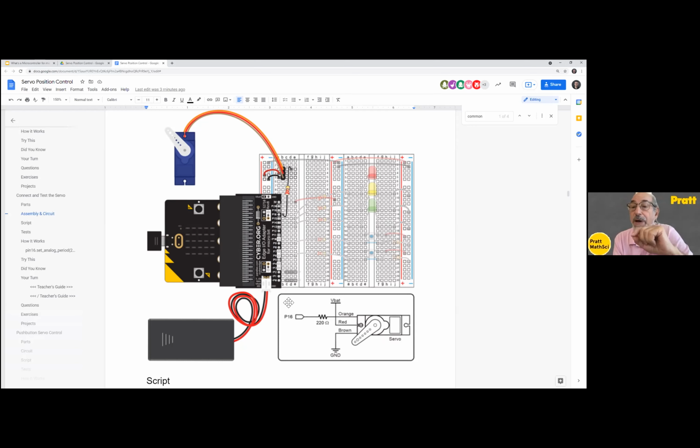Andy, is that you might want to, in a later version of the adapter, have the female connector for the battery pack on a wire even, and instead of having the connector on the board, have a switch right there. Okay. Yeah, those connectors are really made to make connections once and be left alone. Like when you're wiring up a computer, they're really not made to be pulled and plugged in a lot.